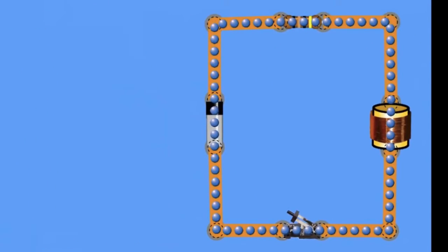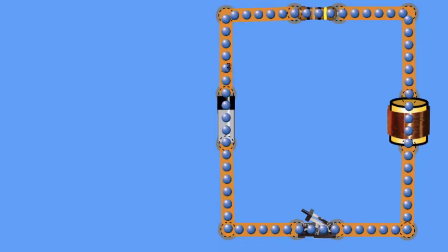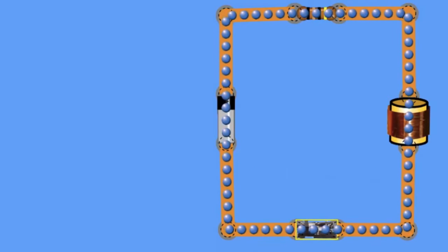If we move over to the circuit on the right, it should be basically the same. That inductor, if we think about it, is basically a long wire made into a coil. So now the circuit is pretty much the same as before: 1 ohm resistor, 2-volt battery, and then we have the inductor. Ideally, it's just a long wire of no resistance. So at first glance, we would expect the same thing to occur when we close the switch.